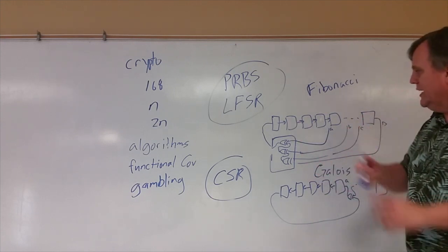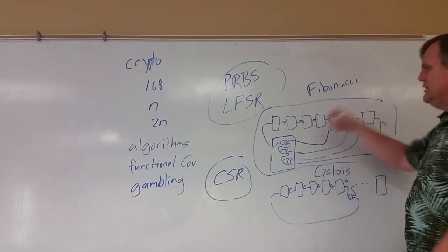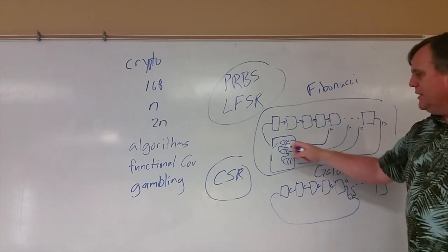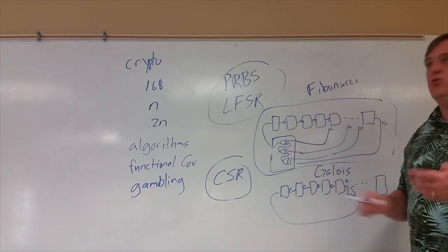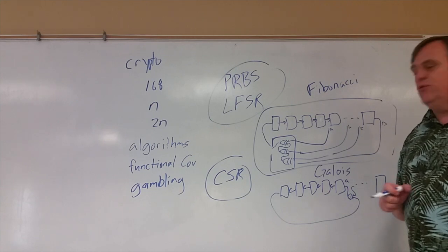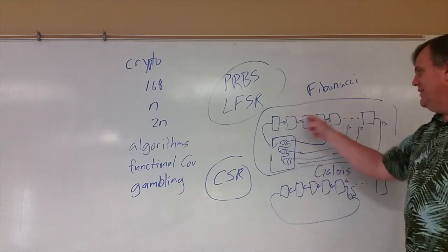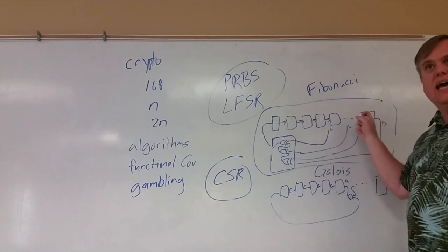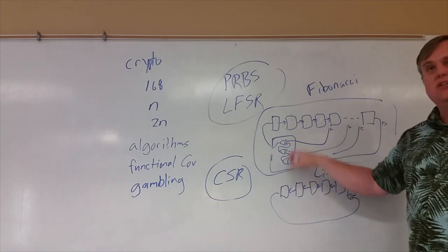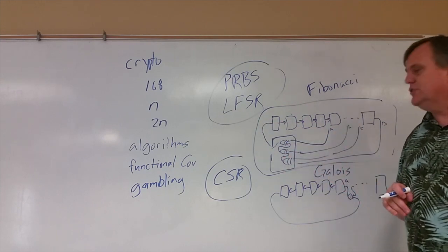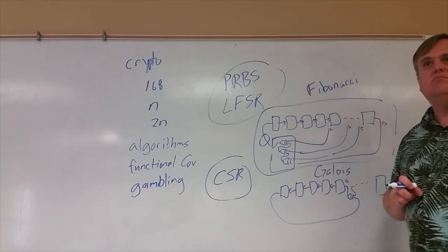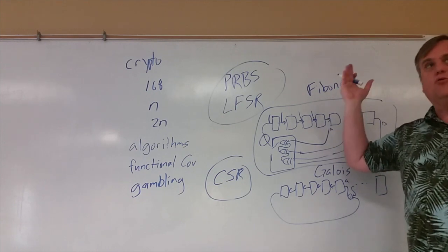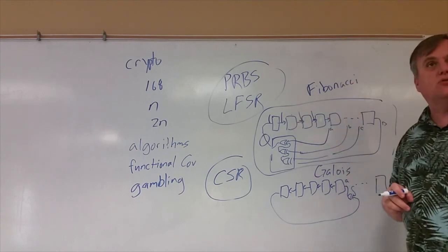So we'll actually do this Fibonacci format here, because it's really simple to make a sequence of these, then draw taps and run them into a giant XOR. Because these cascading XORs are identical to one big XOR, I can write this whole thing in one line of code. It's trivial, just a concatenation of the first half of every string except the last one. You just take all those and concatenate this function at the end of it. That's really, really simple. And classically, you output that bit, although in theory, if you wanted like 12 bits of something, you could just grab the first 12 bits here too.